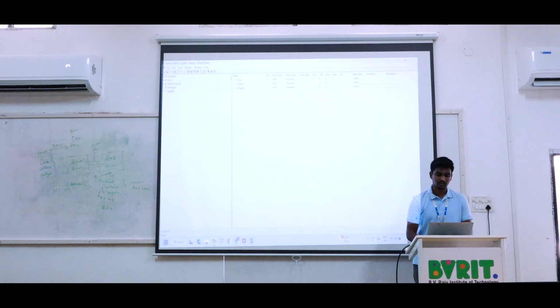So initially it was showing some X mark on the left side. In the signal column we can see the X mark on the left side: log left side, unlock left side, tail left side. If you are mapping that to messages, it will not show. As of now we are not getting any messages here, so it is the indication that the signals are not mapped.